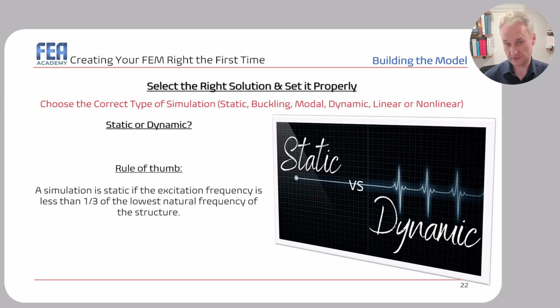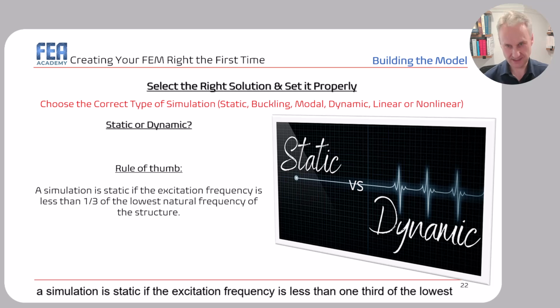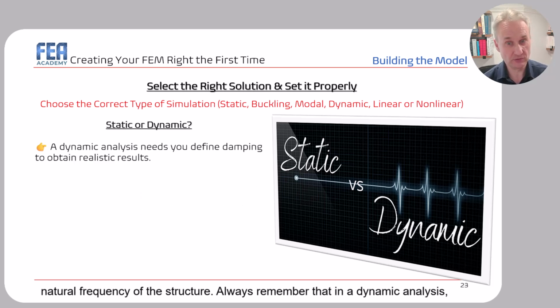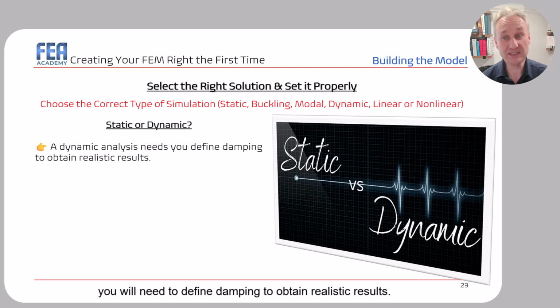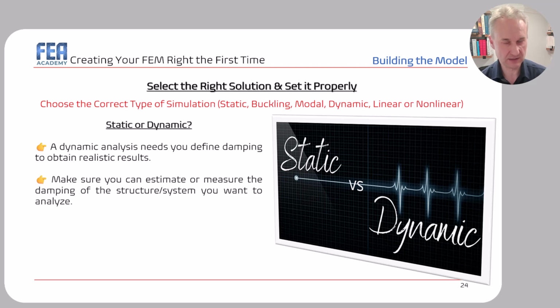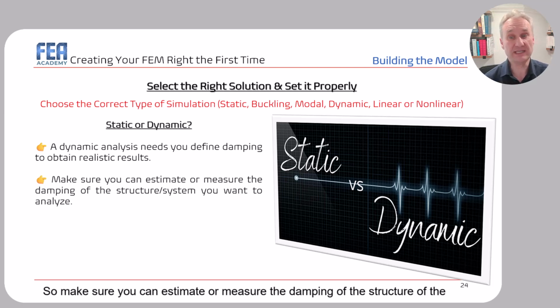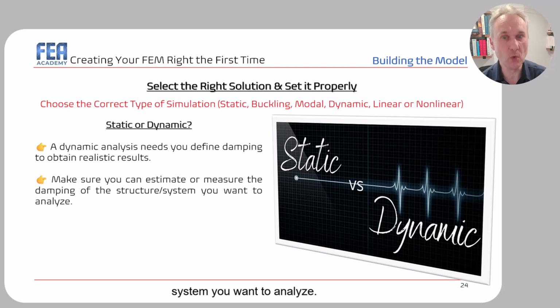As a rule of thumb, a simulation is static if the excitation frequency is less than 1/3 of the lowest natural frequency of the structure. Always remember that in a dynamic analysis, you will need to define damping to obtain realistic results. So make sure you can estimate or measure the damping of the system you want to analyze.